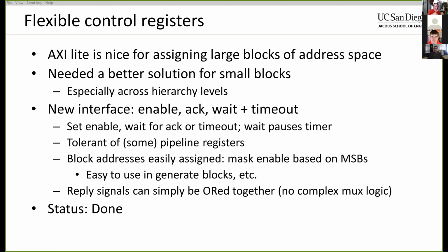I can have multiple modules looking at these signals, and if one of them detects that the address corresponds to one of its registers, it can either perform the operation and acknowledge it, or assert wait, do its internal computation, and then acknowledge and return the result.